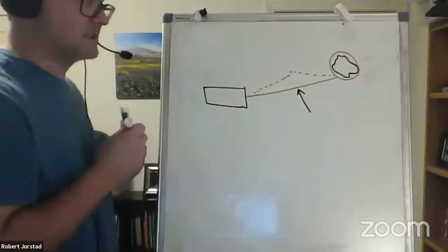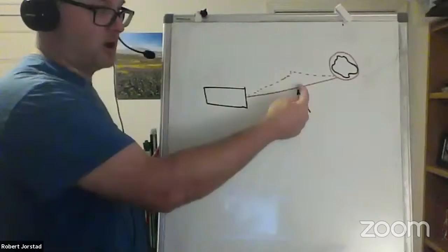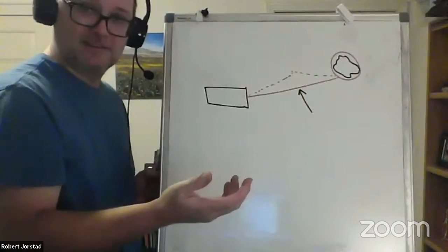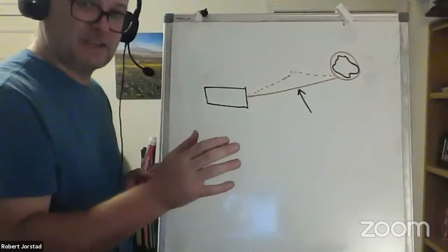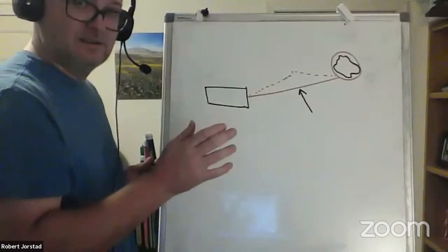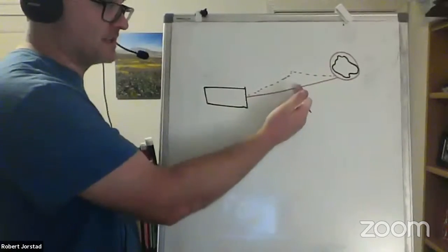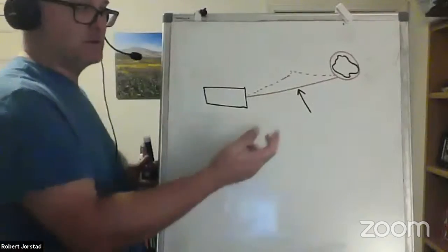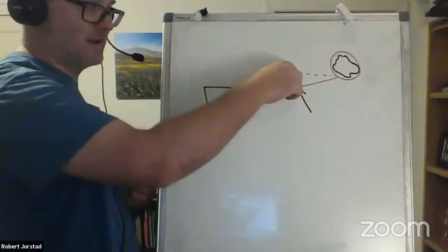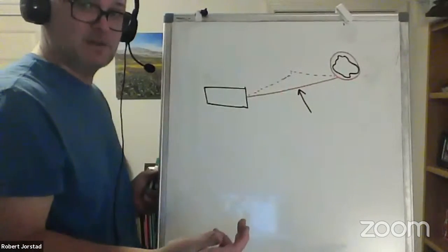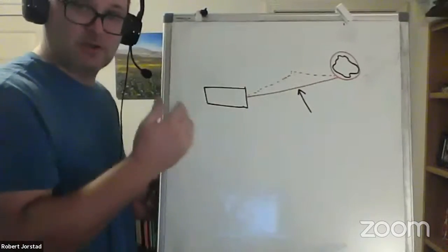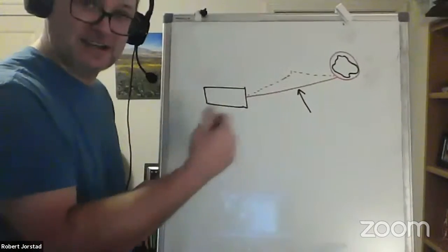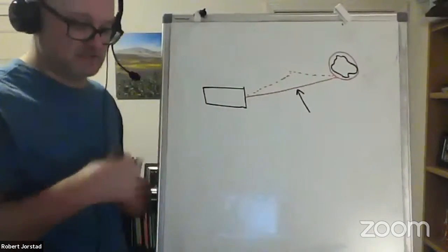Now, when you do this, you're going to apply a small amount of tension here that gets magnified in the other component. Huge magnification. Cool. So the idea is you push on the center of the rope, you get your car to move. The trade-off is you apply this tiny force over this large distance, and then each time your car moves a few inches, you've got to untie the rope and retie it and get it tight again. But it beats being stuck out in the woods.